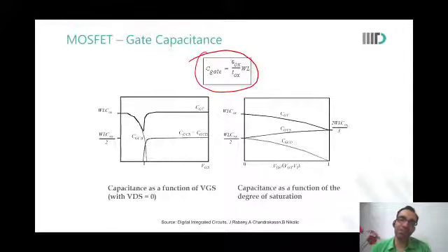Actually, that was my doubt, sir. I didn't know why we were specifying the exact number of contacts. You tell me, what are contacts? They are kind of wires connecting the metal one with the source or the drain. So if you have 1 wire versus 4 wires in parallel, what happens? Resistance decreases. Got it, sir. Thank you, sir.